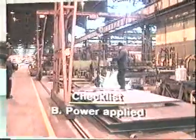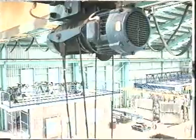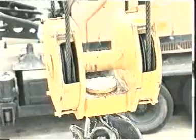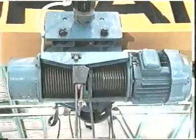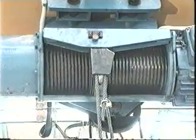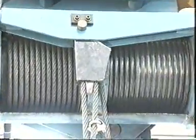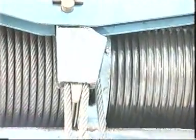Once the power has been applied, firstly, check the operation of the stop button. Then operate the crane or hoist through all motions and pay particular attention to the brakes. The tracking hoist should be smooth. Be alert all the time for signs of machine faults. Odd noises, smoke emissions and irregular movements of the crane are signs of faulty equipment.